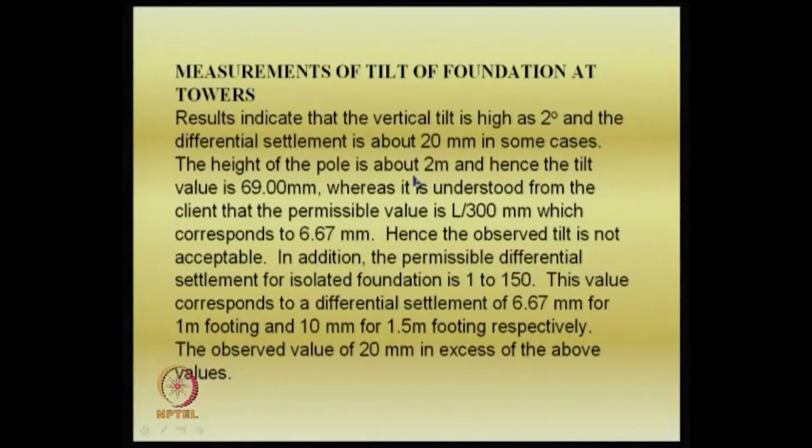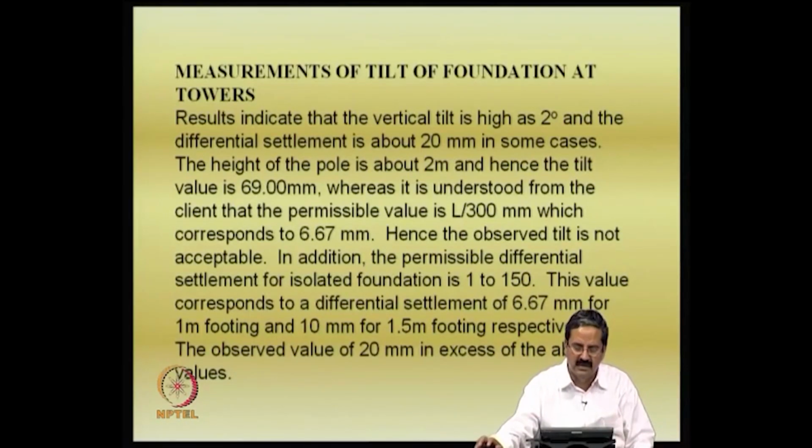See that somehow you bring it back to the original condition, and then see that these limits are achieved for all the poles, and do that lime treatment, because the problem comes from the actual soil itself and it should not occur. So the first thing is that they should be brought back to the actual conditions in some form by loading or removal of soil, and in fact the removal of soil to reduce the tilt was done for the Leaning Tower of Pisa itself.